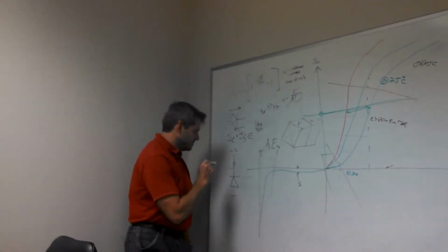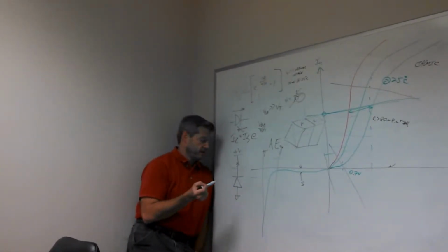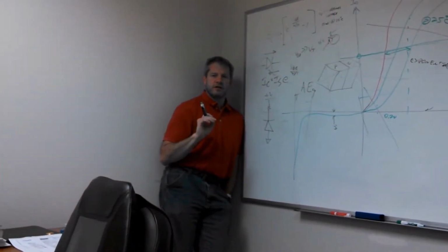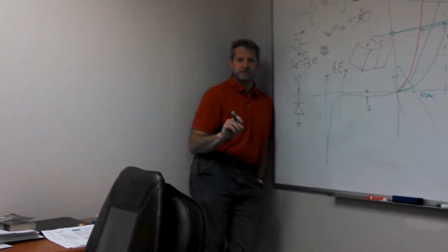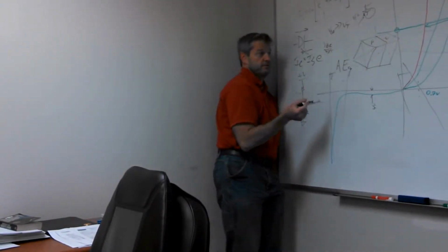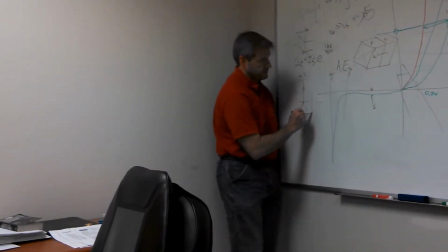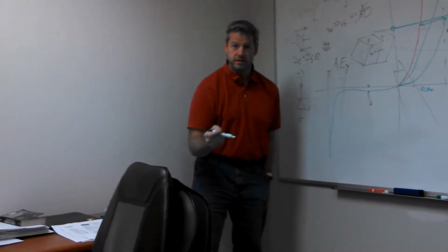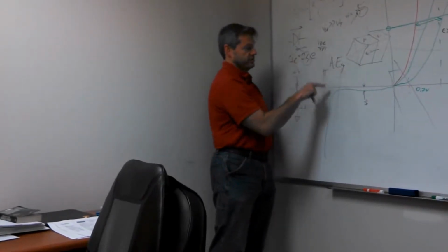At absolute zero, if you could ever get there, no current will flow. There's no molecular motion, electrons are stuck in their bands, and there's nothing to make them move. Anytime you're above absolute zero, you start getting some drift currents this way, and the warmer it gets, the more there will be. So IS is also temperature dependent.